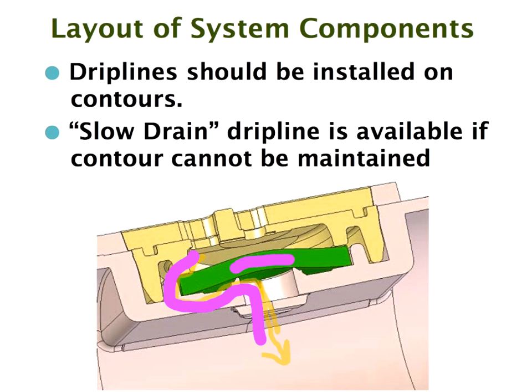This is Rodney Ruskin's personal opinion. I believe that eventually all our drippers will be slow drain. It's my opinion. We'll find out as we have more and more of these systems in the field and we have more experience. But my own experience and opinion is that it's a superior technique and there's no reason not to switch all our pressure compensating drippers to slow drain.